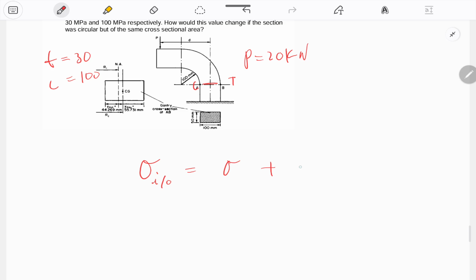And this guy, we know him, that is M times (r minus r_o) over (A e r_o), something like that. Some of these variables I've talked about before. This is your moment, this is your r as in the neutral axis. This one is r, the position you're interested in, and this guy is the centroid, and this guy again will be your neutral axis. And you have a formula to calculate the neutral axis.